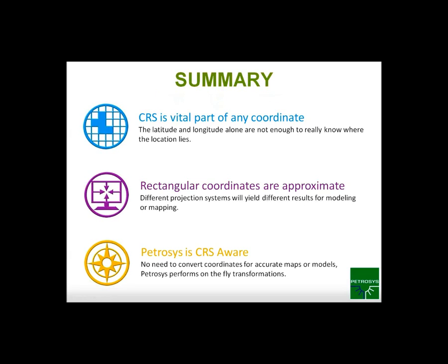So now, finally, I just want to summarize and drive home these points that CRS is really a vital part of any coordinate. Whenever you just get that latitude and longitude pair, it's probably not quite enough to know exactly where that is. You really need to have the geographic CRS as well. Always remember that your rectangular coordinates are going to be approximations. So if you get easting northing values or some sort of XY values, you have to know exactly what